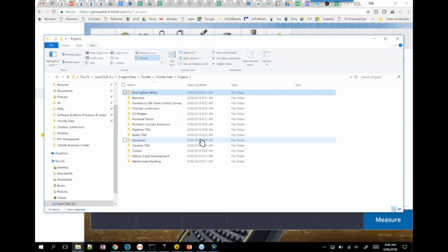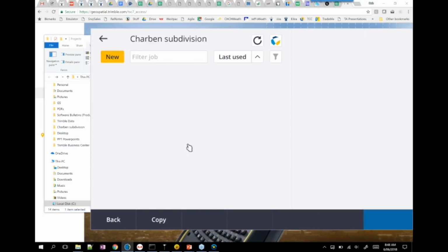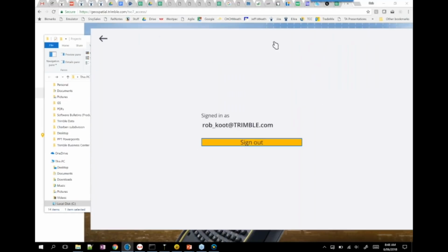And the other little difference there is that when you created that folder in Trimble Access 2017, you were also asked whether you wanted to work online or offline. And if you wanted to do Access Sync type functionality, syncing files, then you would work online. With the new Trimble Access, basically all of that is controlled from within the jobs and project screen. So if I want to work online, I simply log in to connect.